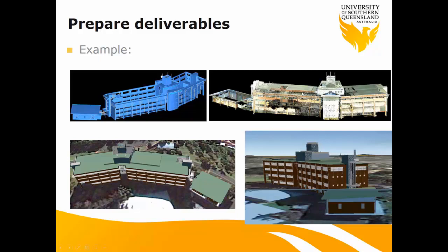So he then did the registration and the georeference together. Why? Because you can see just the registration cannot combine the scanning from the top of this building to the ground scanning data. So that's why he used GPS positioning for the georeference, and did the georeference and the registration together.